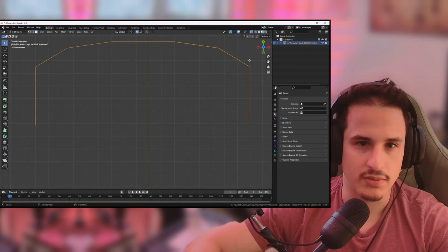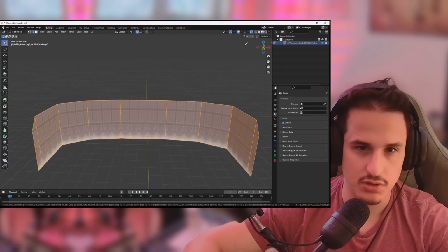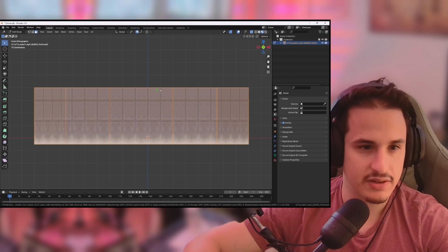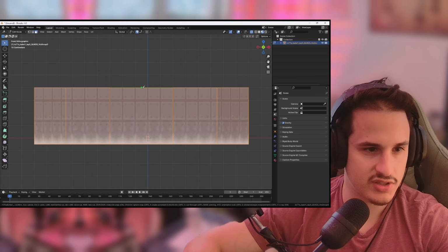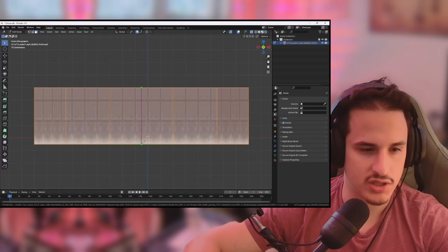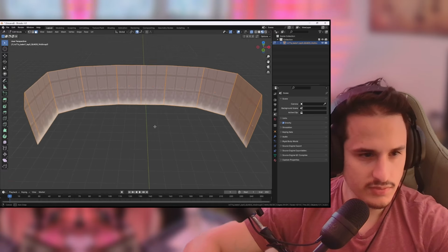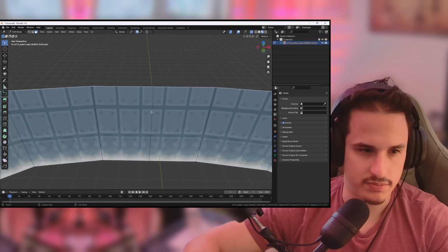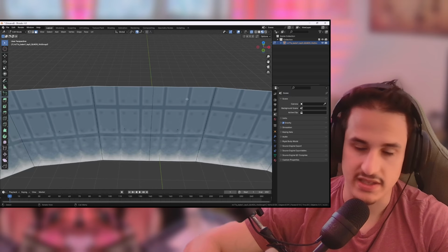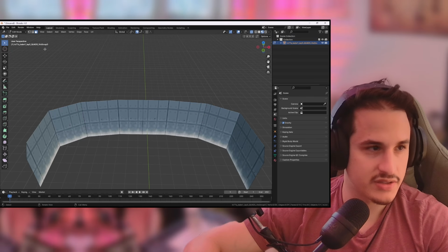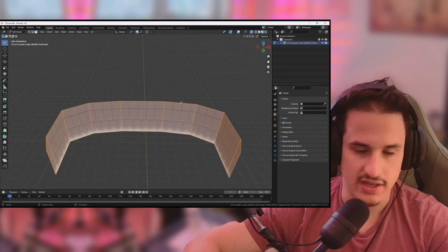If you look from top down, they're angled. The only flat one is here, and splitting this thing might not be easy. So if you want to try splitting things, you can always use the cut tool. That is K, which gives you this knife, and then if you hit shift, it'll get you into the very center. Hit C to make sure you cut through, and then hold shift again, click again, and you'll notice it cuts it in half. But it doesn't quite cut it right down between where these repeating tiles occur, and so that's going to be kind of annoying.